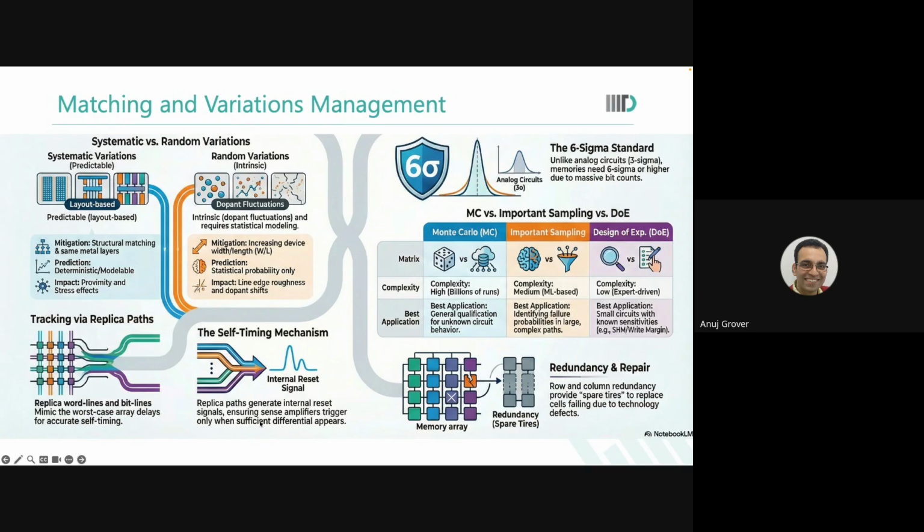In our linear thought process, we solve it one way. But when pushed to a corner, we start to apply multiple instances. So we've applied the principle of a new dimension appearing and symmetry in synthesizing things. Are you getting it? In most modern designs, you will see that the word line is tracked, it's brought back, and then it triggers a replica pipeline. And now do you realize it is very simple?